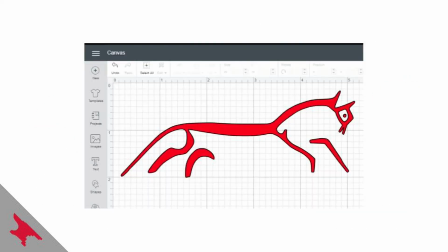For a little more detail, vinyl cutter software usually sees both the outline strokes and the fill colors in your imported vector drawings. The original color is shown, but only the strokes really matter because that's where the machine will cut whatever color vinyl you actually loaded into the machine.